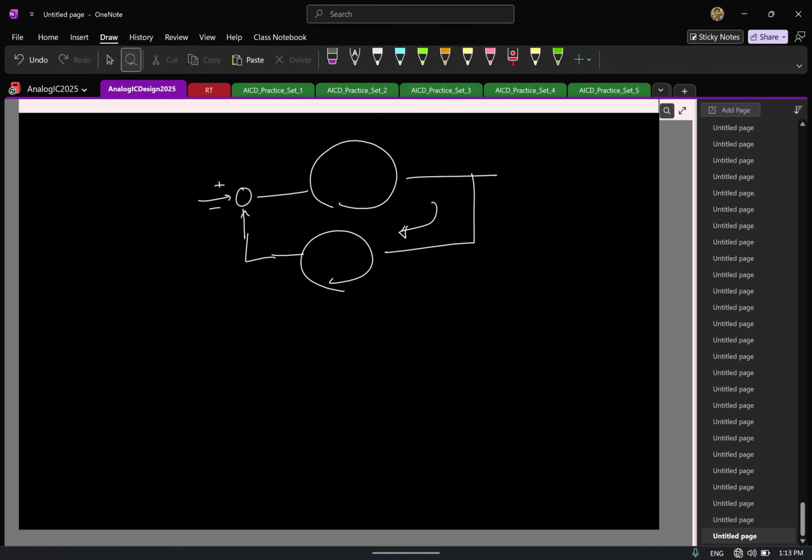If you are doing it fine, the temperature reaches the correct value. Now let us say you are doing it very slow, in slow motion, which means there is a lot of delay in your sense and feedback path. So there is a lot of delay in the loop. Let us say the water is initially cold. It started to increase. Now you dip the hand and then take it out, and there is a slow action there. Now what will happen?